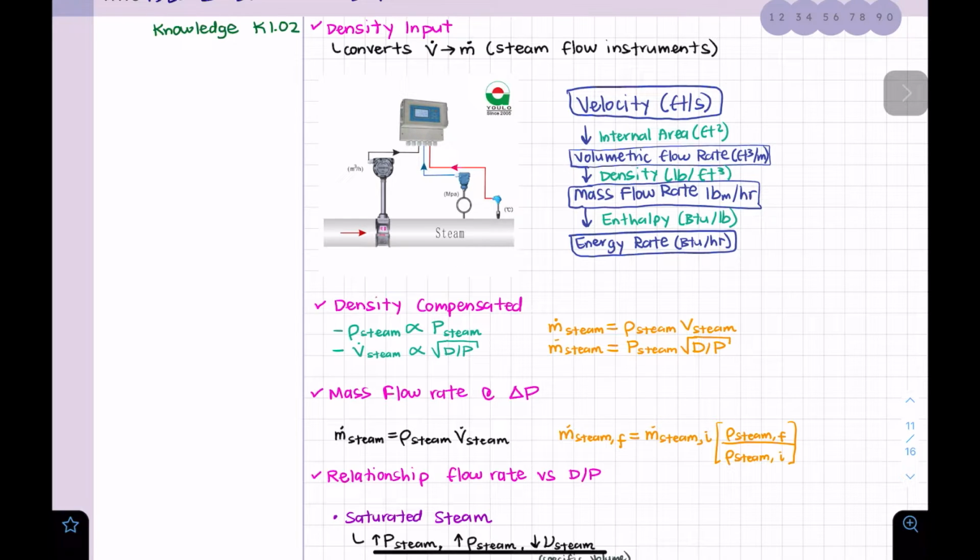So here, what we're trying to measure, the steam. The steam is a compressible fluid, so therefore, if we have a reduction in the pressure, this is gonna result in a reduction of our density, right? So that's why we have those type of instruments. So temperature and pressure in this thing are gonna be dynamic, are gonna be changing, right? So that's why it's important to calibrate the equipment because this can result in a considerable difference between the actual pressure and the meter design parameter. So it's important to always calibrate this type of equipment.